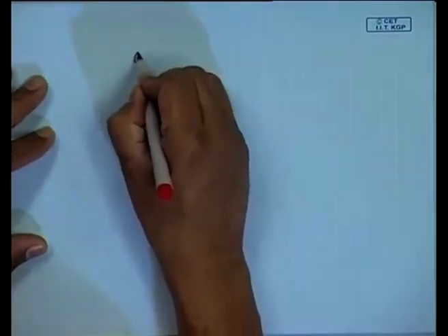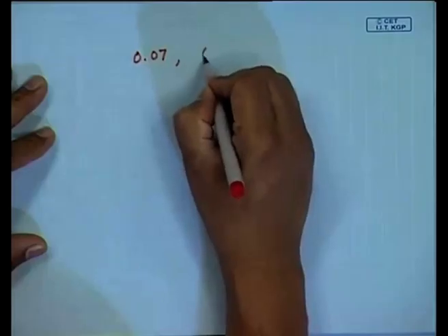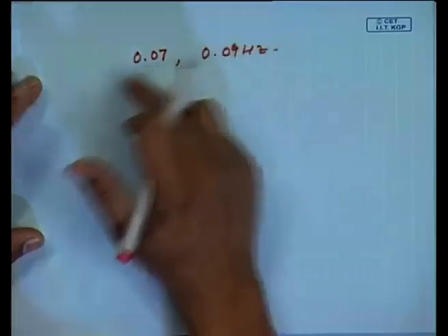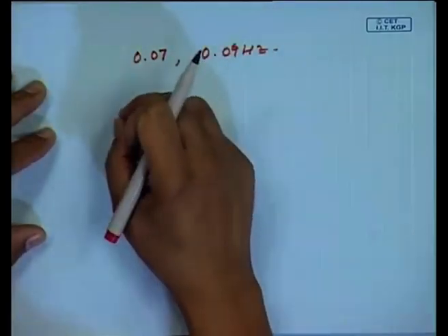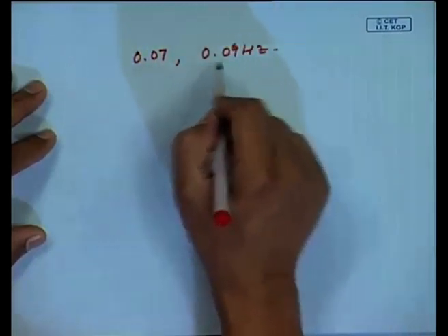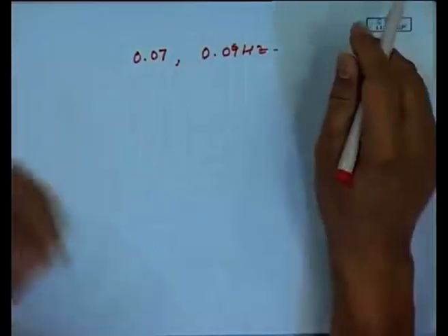Of course, increasing the block size means more time, that is well and good, but then I should not be missing any frequencies. There are signals, particularly when we have the space shuttle, very massive bodies, where there will be natural frequencies of the order of less than 1 hertz, maybe 0.07 hertz and 0.09 hertz. Low frequencies that are two distinct and closely spaced frequencies. So, if I get a vibration signal from a space shuttle, I should be able to distinguish between 0.07 hertz and 0.09 hertz. So, this is a challenge to do.